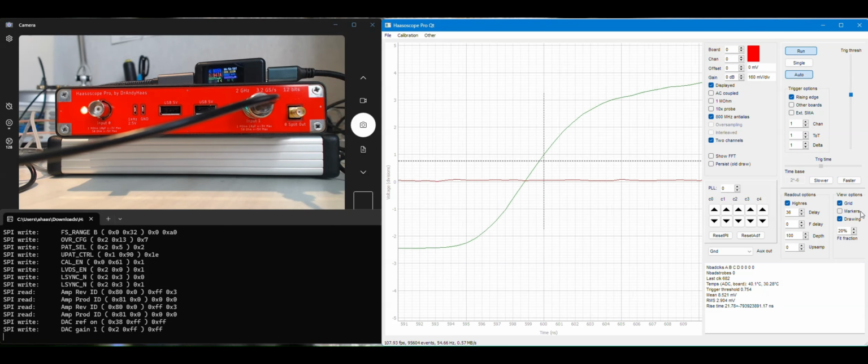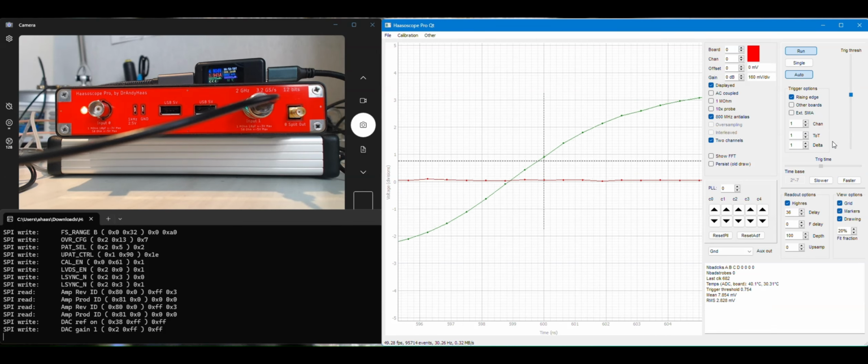Great, so now we've got both of those, and if we look at the sample rate, it has been halved. If we draw our markers again and zoom way in, we can pause. You see that in 1 nanosecond here, we only have 1.6 samples, whereas before we had 3.2 samples in a nanosecond. So we did halve our sampling rate.